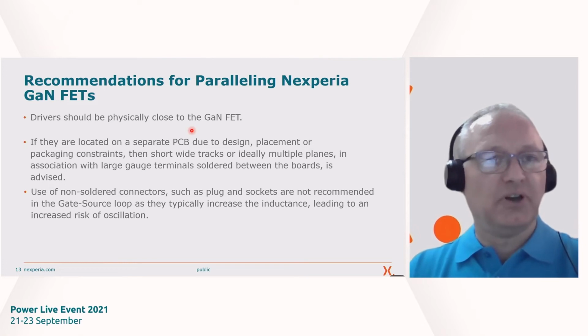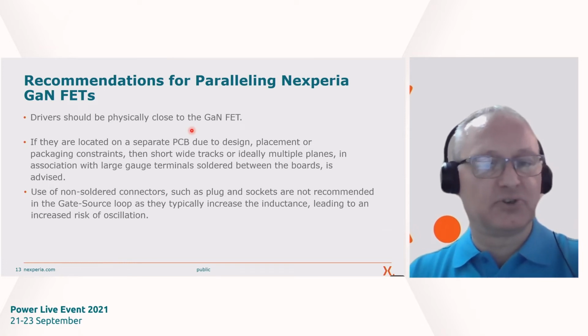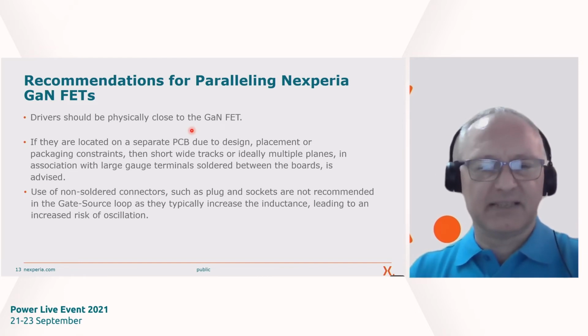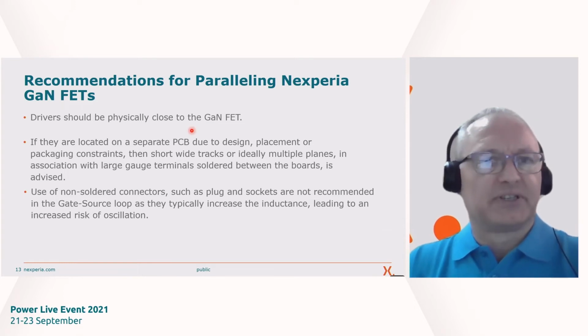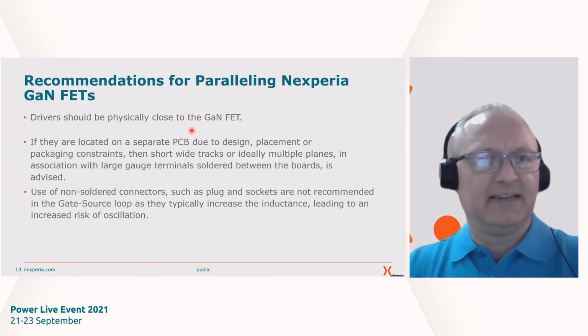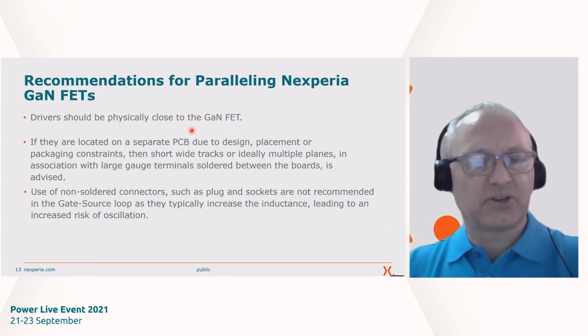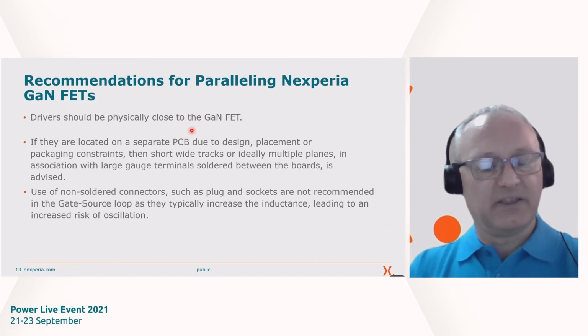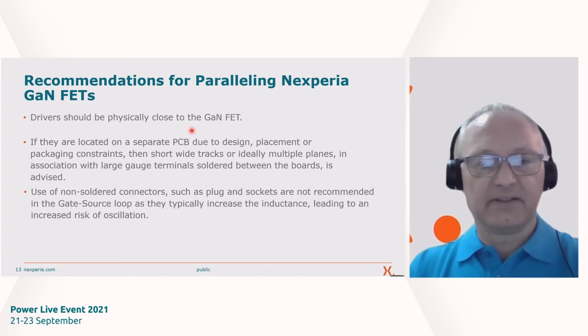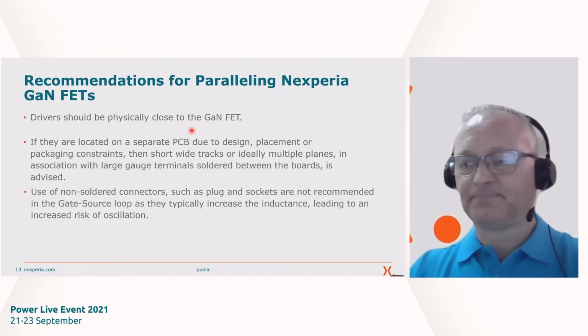The use of non-soldered connectors, such as plugs and sockets, is not recommended in the gate source loop, as they typically increase the inductance, and that does lead to an increased risk of oscillation. And that was actually seen during the validation tests that I performed in our lab.